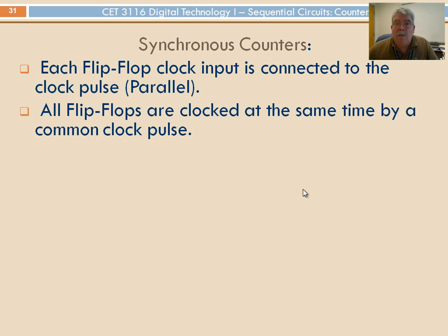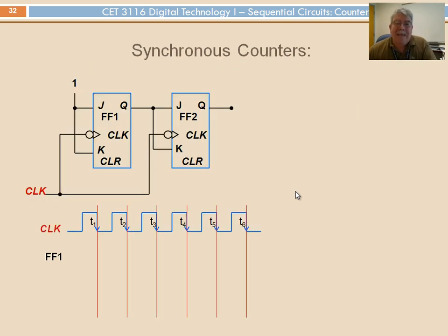All right. Let's see one example, very easy, of how a 2-bit synchronous counter is set up. We have these two JK flip-flops. The first flip-flop is set to toggle as before. However, the second flip-flop is not. It's fed directly with the JK tied together, but not necessarily to 1. Remember, the first flip-flop's Q is going to be toggling, so Q is going to be changing from 0 to 1, 0 to 1, 0 to 1.